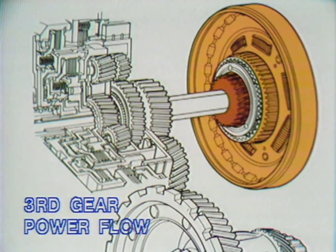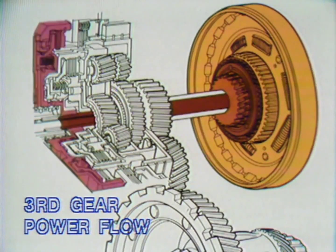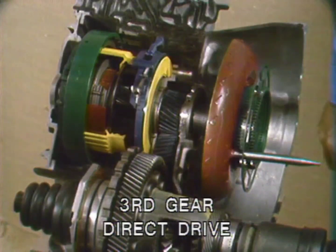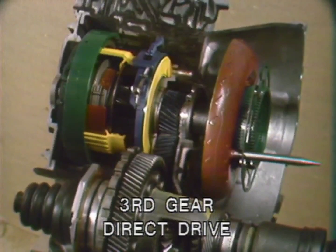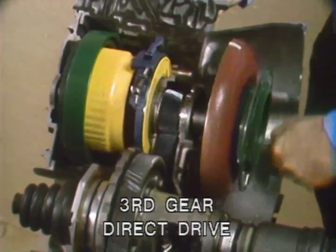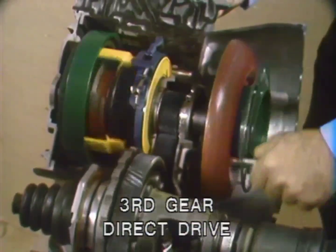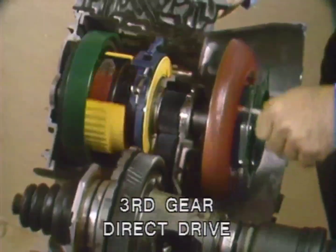High gear power flow is from the converter turbine and cover to the splitter planetary unit, then to intermediate shaft, intermediate clutch, ring gear, main planetary unit, and final drive. Watch as Joe demonstrates. He has locked up the direct clutch and the intermediate clutch and is turning the intermediate shaft with the turbine. This simulates a coupling condition in the torque converter, which is what causes the main gear train to lock up. One turn of the input shaft equals one turn of the final drive input. The gear train is locked up in high gear.